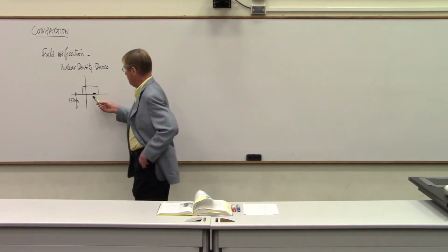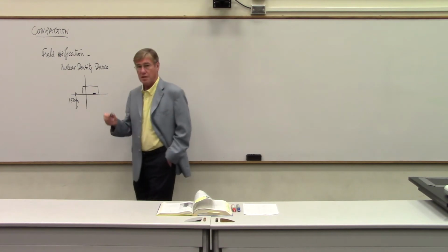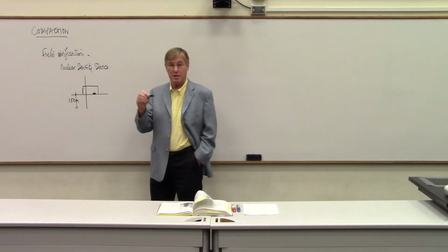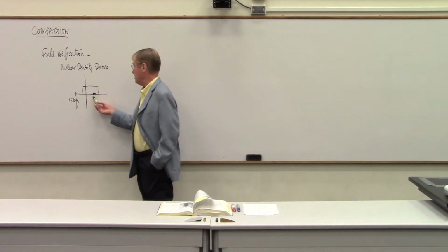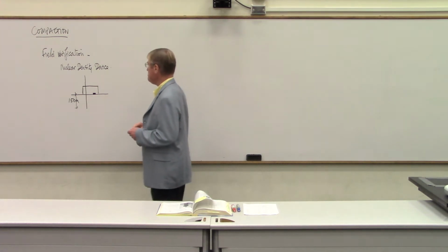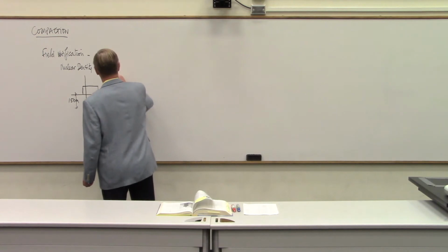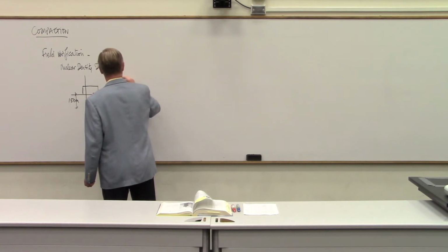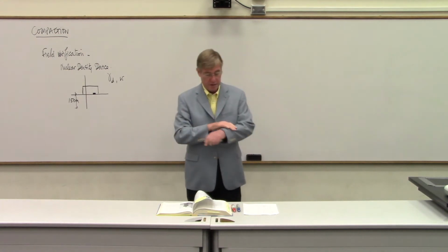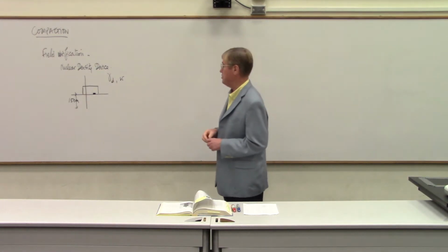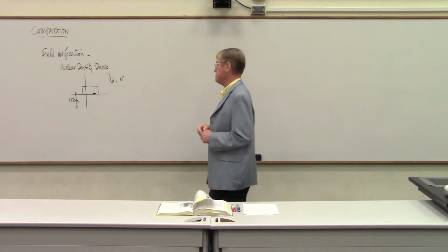In other words, if the material is very dense, then the rays will bounce back and forth and will not get to the receiver. And this tool is used to obtain gamma D and W. So that's how you verify that you have obtained what is necessary in the field.